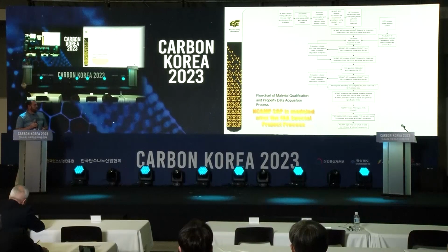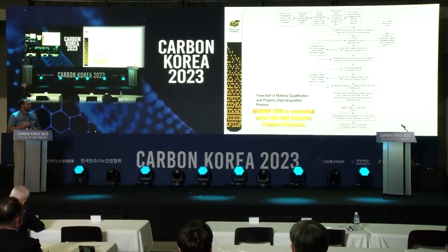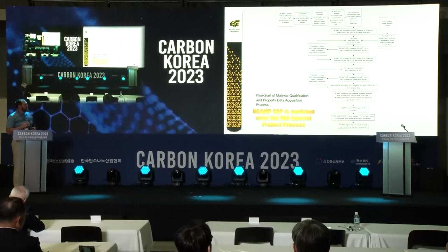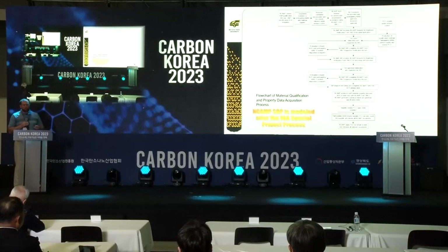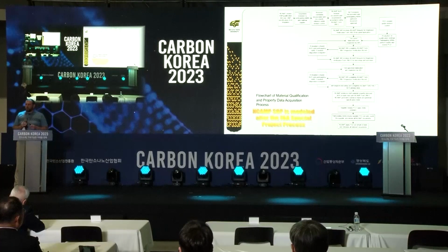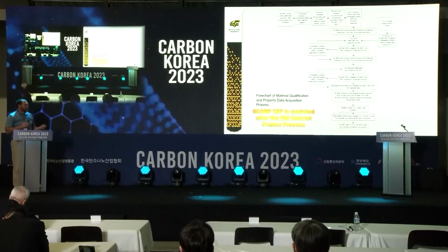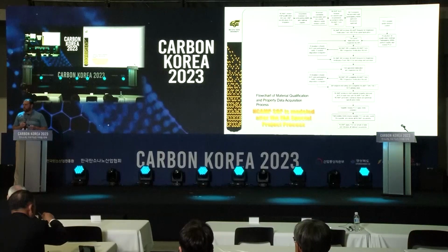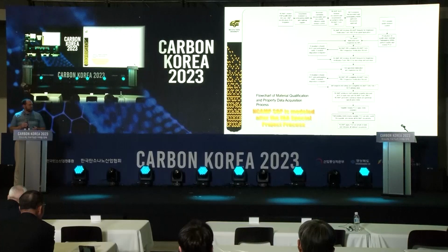This is just a flow chart that gives an idea of the steps involved with creating a material allowable for a particular material and process, starting at the very top with the introduction of the material to NCAMP, flowing through various conformity steps, whether that's creating panels, creating coupons, or conforming the test setup, making sure that all of that is done in an appropriate manner. And then all the way down to where we are generating the specifications as well as the material property data reports that are all published on the NCAMP website and then are allowed to be used once published by the various industry partners.